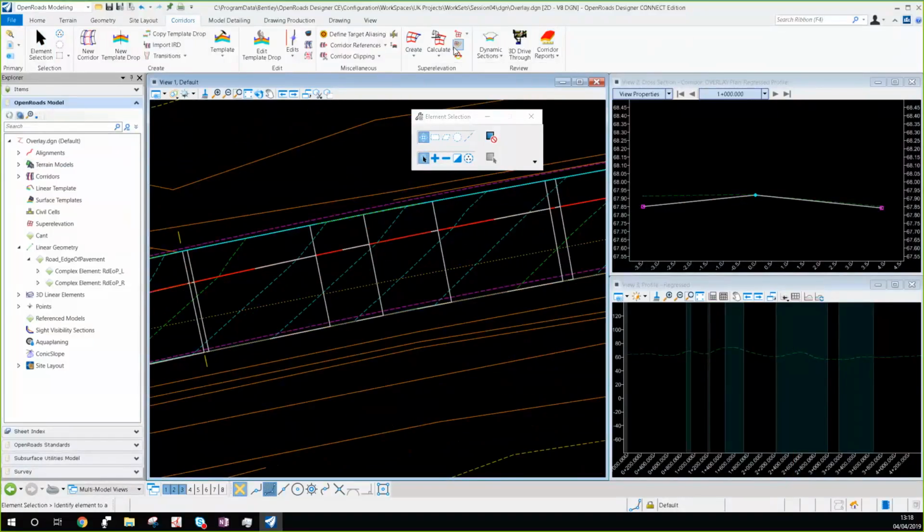So the super elevation command tools are here. You have different steps to follow if you want to create a super elevation. The first step will be to create a section. Then in these sections you will have to create lanes, and once you have your lanes you can calculate the super elevation for each lane, and at last you can assign these super elevation lanes and section to the corridor.